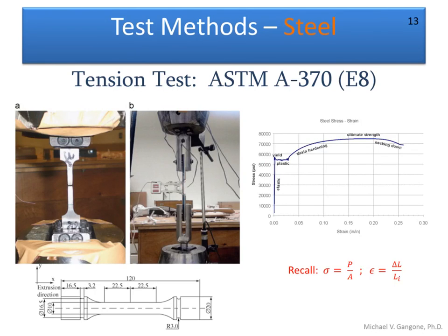Okay, so these are some of the common things we get out of the stress-strain curve. Now again, we start out here where we see the linear part of the curve. This is the elastic region. So this is where the material is elastic. So if I remove the load anywhere within this particular line, say we're up to 50,000 pounds, and we release the load, then the specimen should go back to zero deformation. Okay, so it remains elastic. Then we are eventually going to hit a yield point, where we reach a point where the deformation continues to increase under a constant load. All right, so the load's not changing, but the deformation keeps increasing at that particular point.